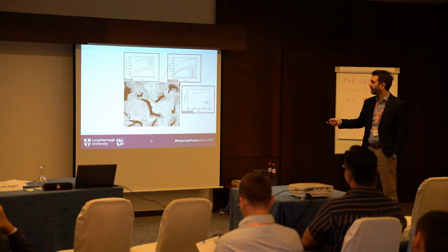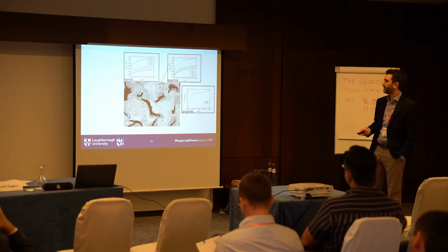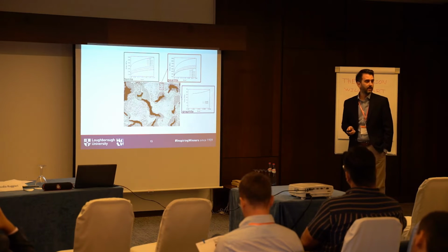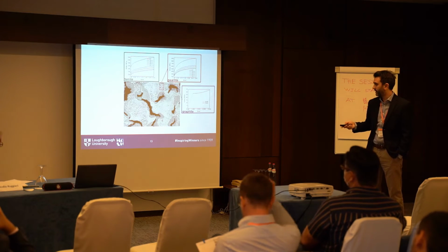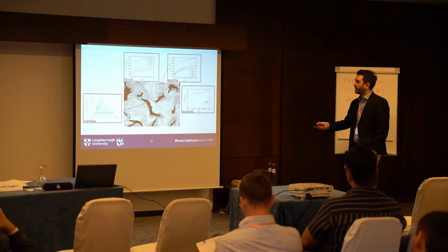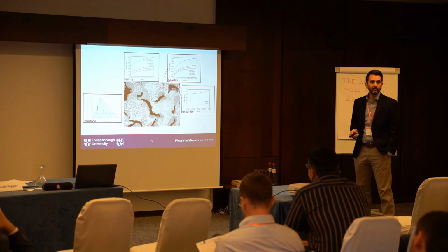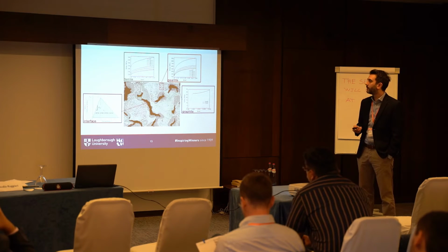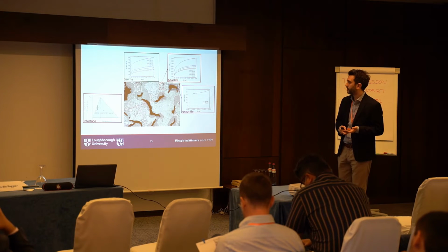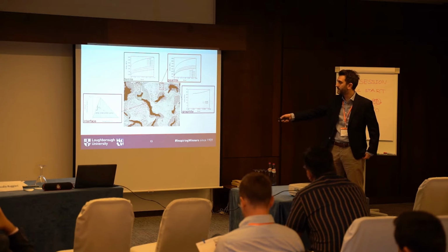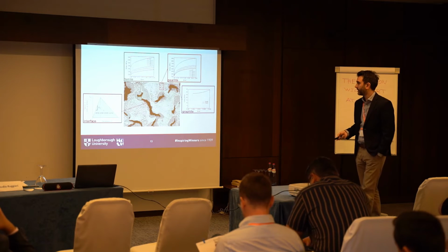And then we have the graphite. Unfortunately for graphite, we don't have any temperature dependent data. Graphite is mostly elastic, and then with a very limited plastic portion, brittle fracture there. And on top of that, you can have some interface simulated by some cohesive elements. Now, another trick on how to find these properties for the cohesive, remember the discussion in the plenary this morning about nano indentation, literature, and so on. So this is a study on its own, I would say.